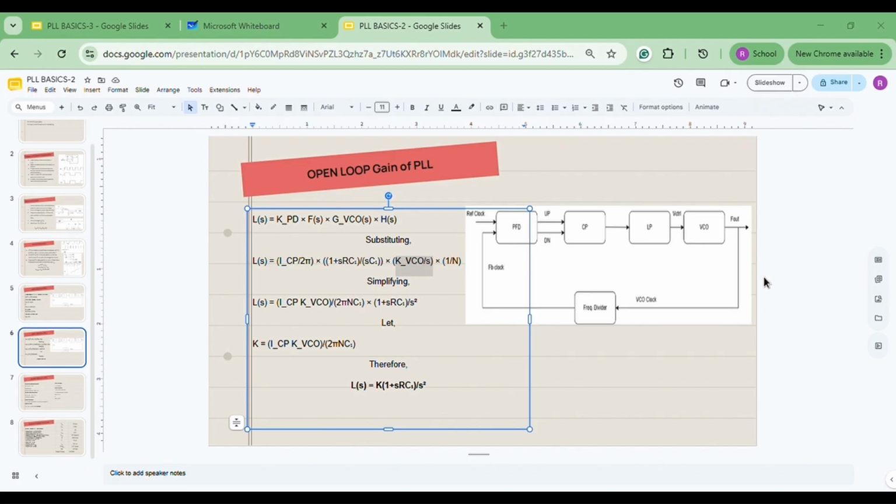When you right click, direct plot, main form, then you will get these add to outputs options. So you can add to output or plot also. You'll get a phase response and gain response. Here, this also I have not discussed, so let's discuss this plot.